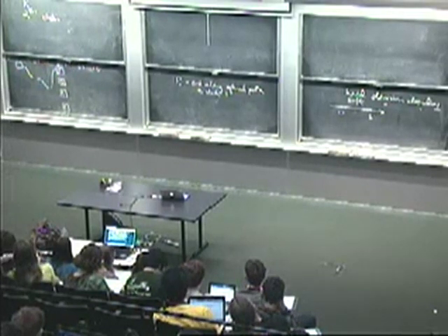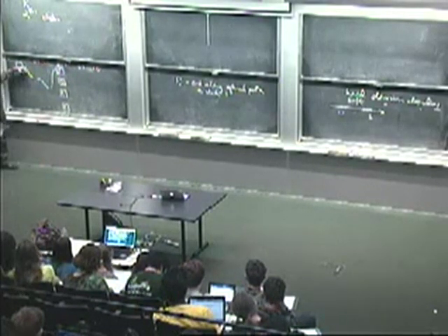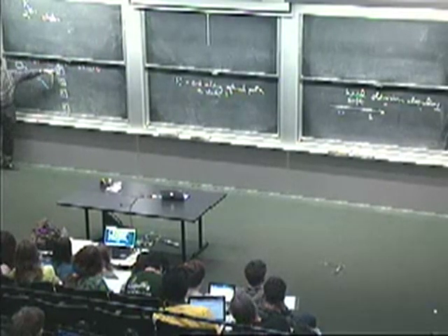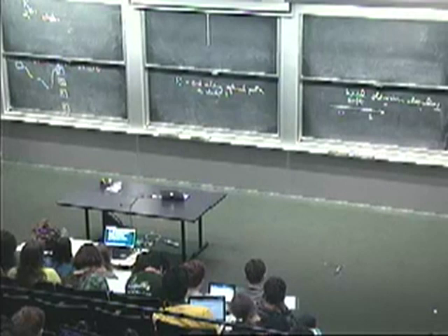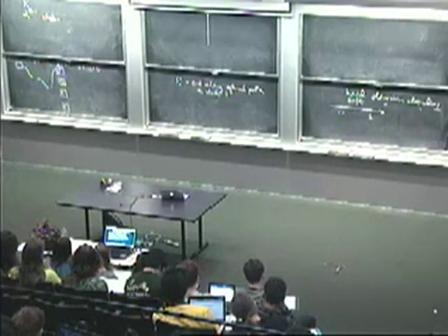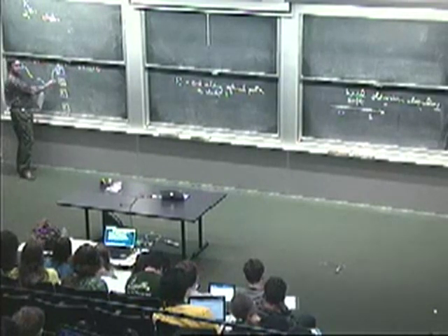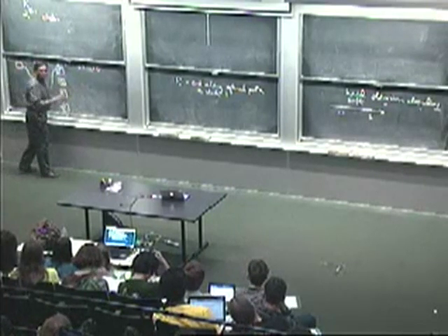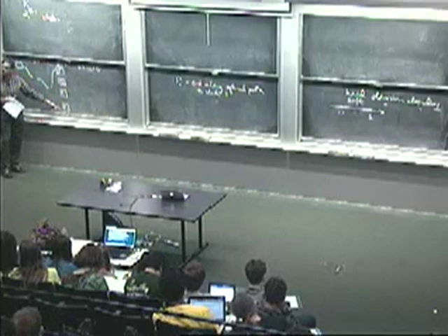Okay, now what do I mean by cost? I just mean Hamming distance between what I've received and the parity bits emitted along the way up to that point. So Viterbi is going to keep track of this for every stage as you step along, and for every one of these states.